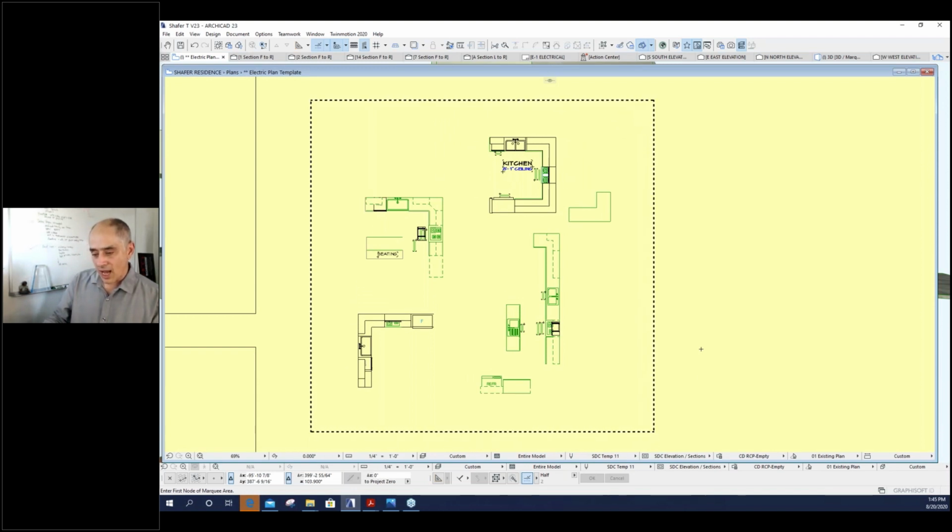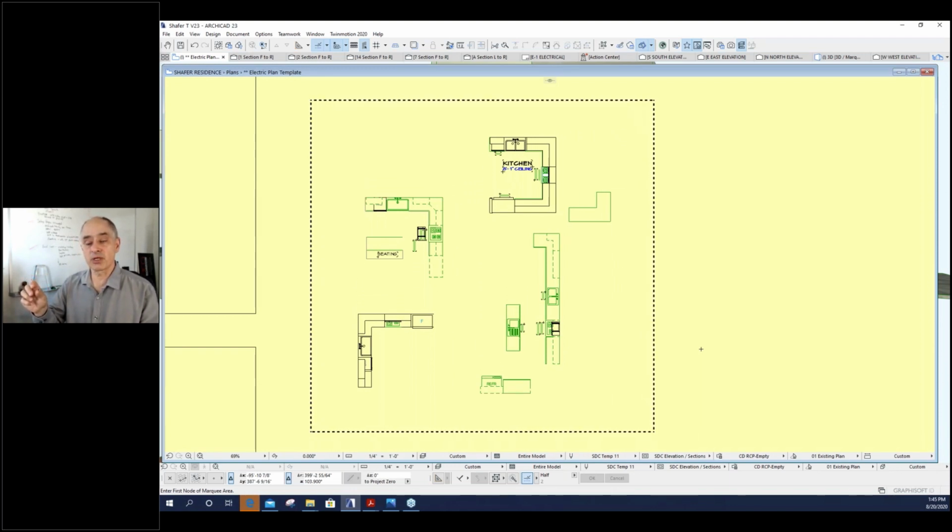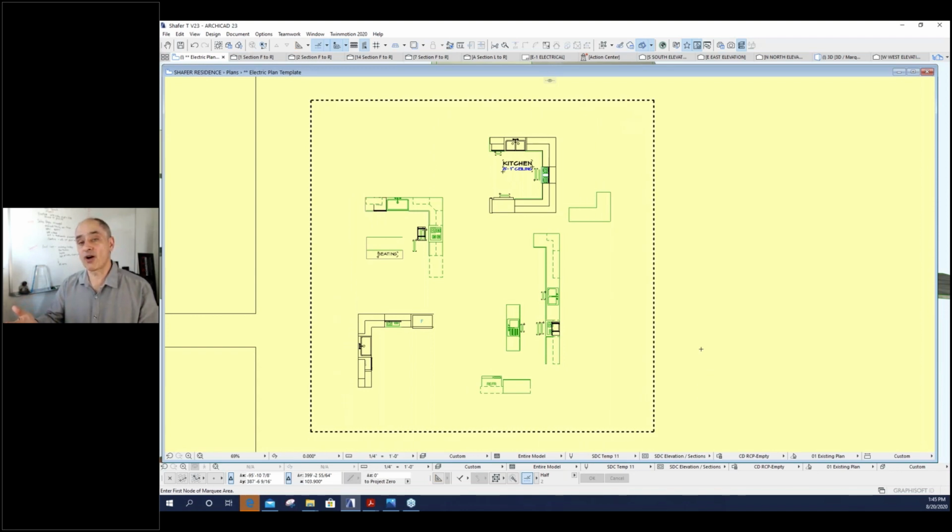Okay. Todd says, how do you transfer favorites from a project to use in a new project? So, very quick little teaching tip. If you have the favorites palette open, there's a little pop-up in the upper right that allows you to do some management. One of them is export, and you can export either the whole set or just a few items that you know were added, and you save it out to a file. In your other project, that same menu allows you to import.